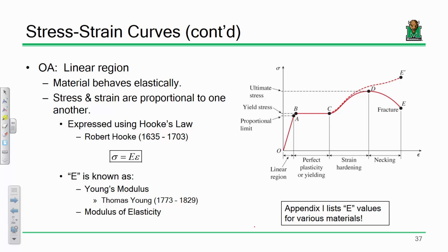We do the same thing in civil engineering when we're designing buildings and seismic applications. When you have a building that's subjected to a really large earthquake, as structural engineers, we don't care if the building has to be completely rebuilt from the ground up, just as long as at the end of the earthquake nobody died. When you look at some of the forces that are generated from earthquakes, there's no way to design a building so that it would remain perfectly intact and elastic all throughout an earthquake. So you start selecting elements in the building and say, I want those elements to fail before everything else does. Those are some specific instances, and plus I just figured I'd throw some cool stuff at you. But in most applications, we're going to keep everything elastic.